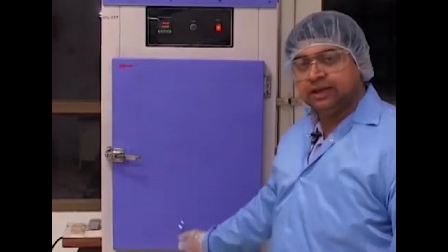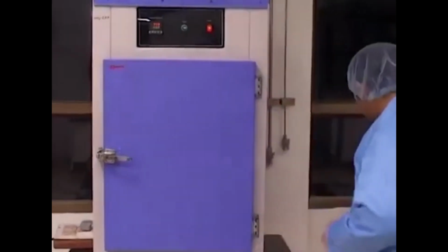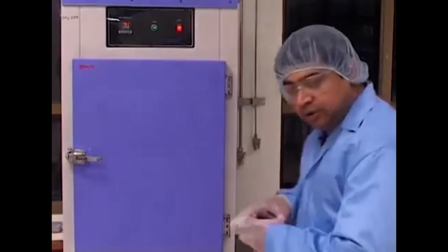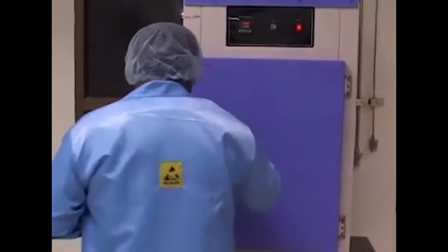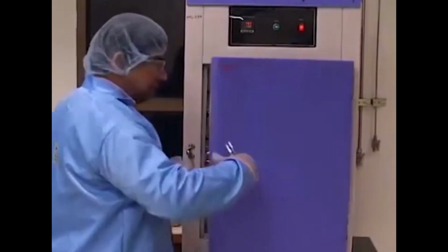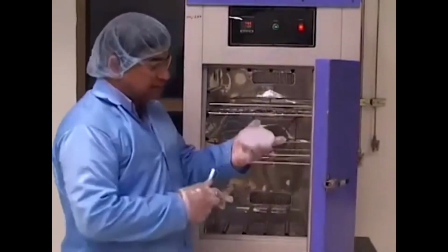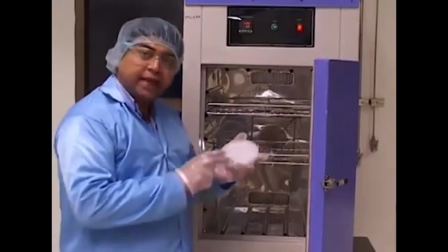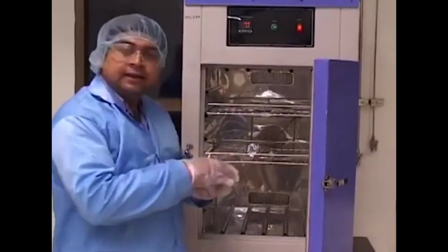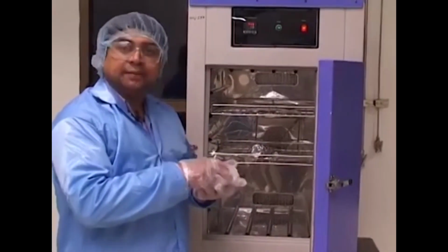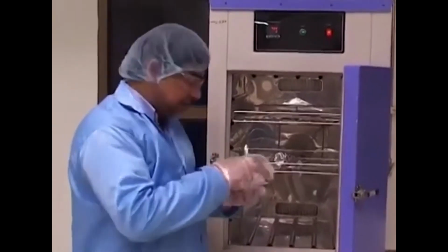So we keep the wafer in the oven for dehydration for about 10 to 15 minutes at about 99 to 100 degrees Celsius. The next step is to unload the wafer and start doing what we call spin coating of the photoresist. So what I am going to do is just unload it and carry it back again. Please note that we are using the same wafer box for carrying the wafer, with the constraint that it should not get contaminated while going between operating stations.